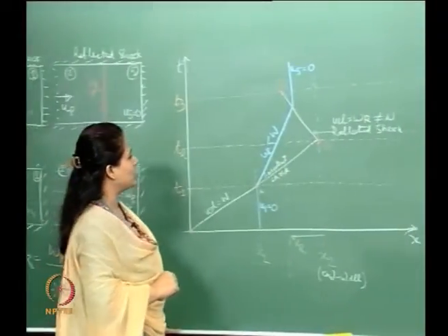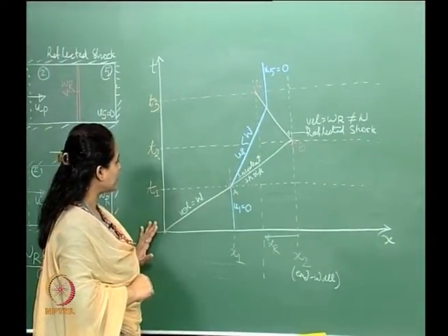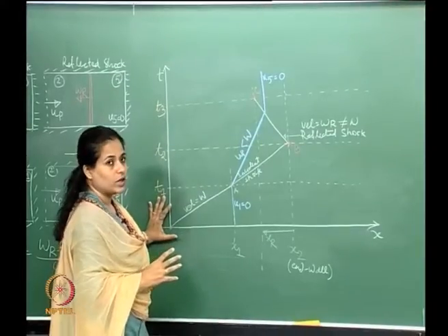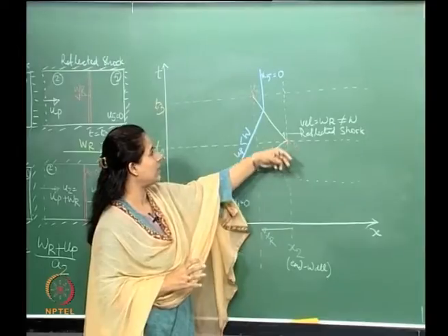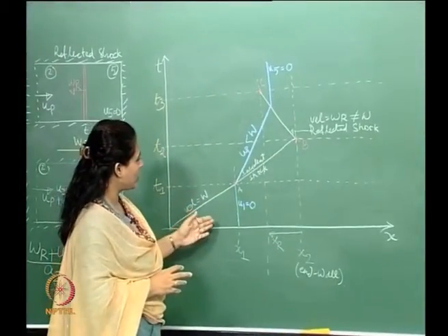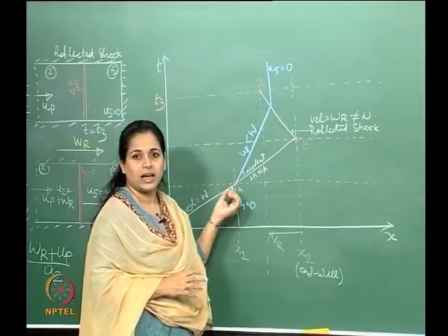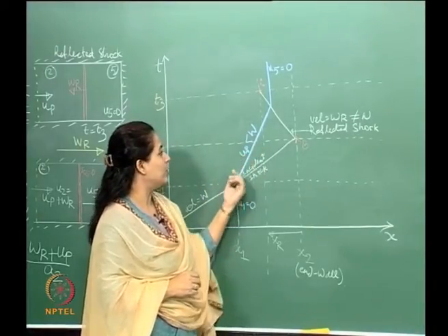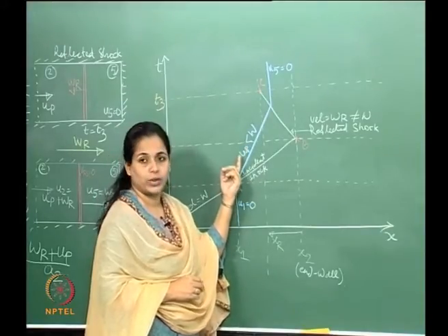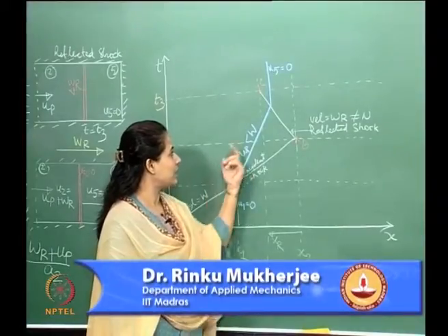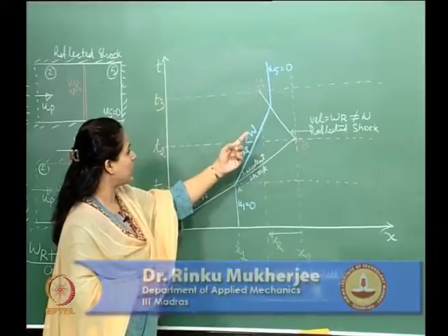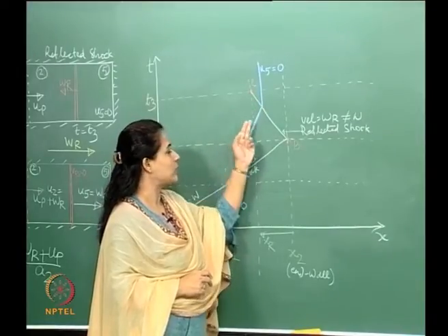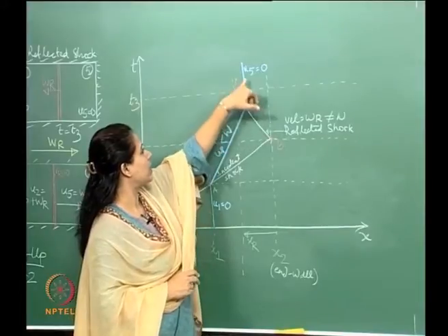So again here basically what you can see is that this could also call for interaction of shock waves, because you have this incident shock wave that reflects. And what you see over here is a fluid particle which was originally at rest. It was displaced from its position by the incident shock, and it starts traveling with a velocity up, which is less than that of the incident shock. It would have reached the end of the tube, but before that it intersects another shock wave, which is the reflected shock wave. And what that does is completely stop this particle in its path, and therefore the particle again continues to be at a stop.